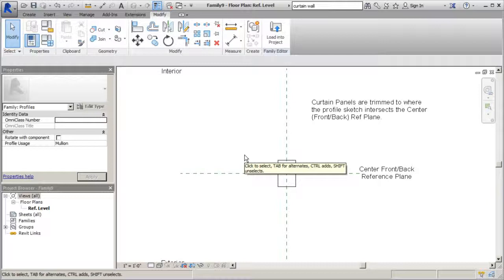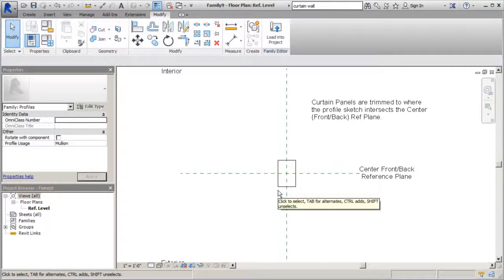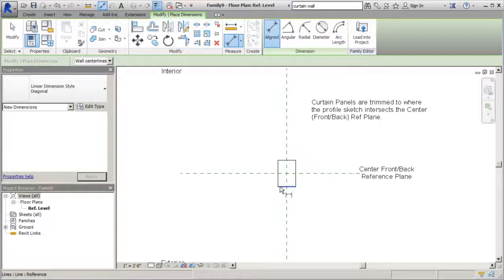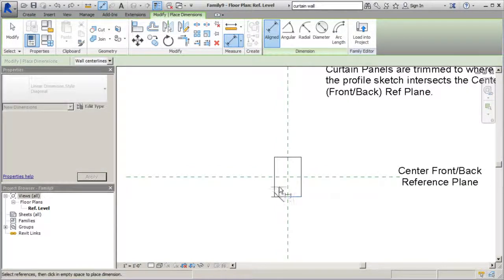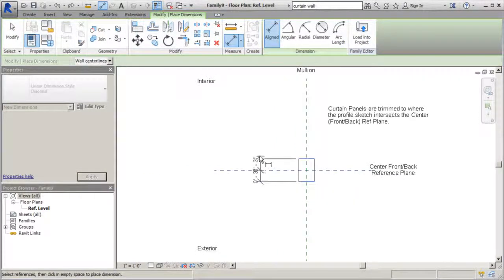Now we can add a few dimensions. When we do this, we're going to add an overall dimension as well as a dimension of equality on both this side and that side. So let's add those dimensions really quick. We'll go from this to the midpoint to here, drag it out, and make it equal by clicking on equal. Actually, I want to drag that out a little bit further. So we'll go there, midpoint to there, drag it out. There we go. And we'll do the same thing in this direction: from this side to the center to here, and we want that equal as well.